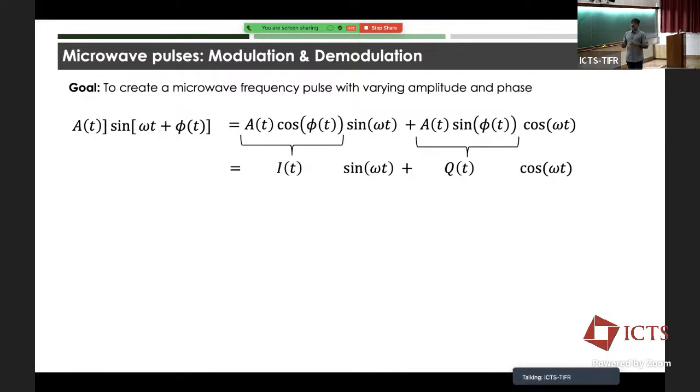Yes. Yeah. Typically, it's assumed, because if you go back and think about AM modulation and FM modulation, typically the modulating signal frequencies are lower than the carrier frequencies. But this formula, of course, actually works for any frequency. You could have very high frequencies here, but then it's difficult to visualize what we are doing. What we are thinking about here is that I have a high frequency signal at ω, and I'm slowly varying its amplitude and phase. Slow here could be 10 times slower, 100 times slower, or maybe even similar speeds. But typically, that's the regime one works in.